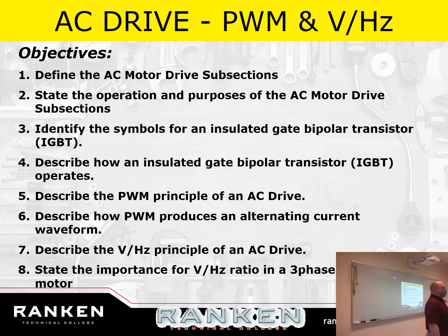The converter takes the AC, three-phase or single-phase, doesn't matter which, and converts it into DC. The DC filter then filters it and turns it into viable, pure DC. And then through the filter, it runs through a series of transistors called IGBTs that invert it back to what we call PWM, or it converts it back to, let's call it synthetic sine wave or synthetic AC.